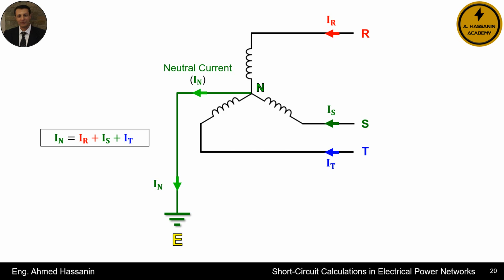However, in the case of unbalanced loads, where the currents in each phase differ, the current flowing through the neutral line will also be the vector sum of the 3 currents in the 3 phases R, S, T. We further emphasize that this applies to normal operating conditions, not during faults. Therefore, it is incorrect to refer to the neutral line current in this case as zero sequence current.